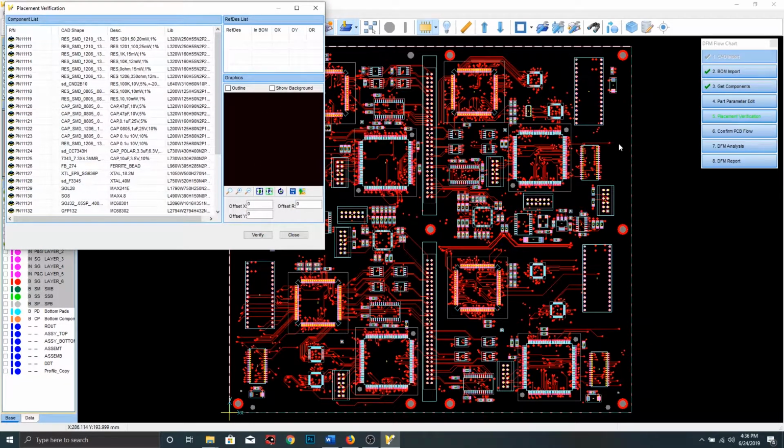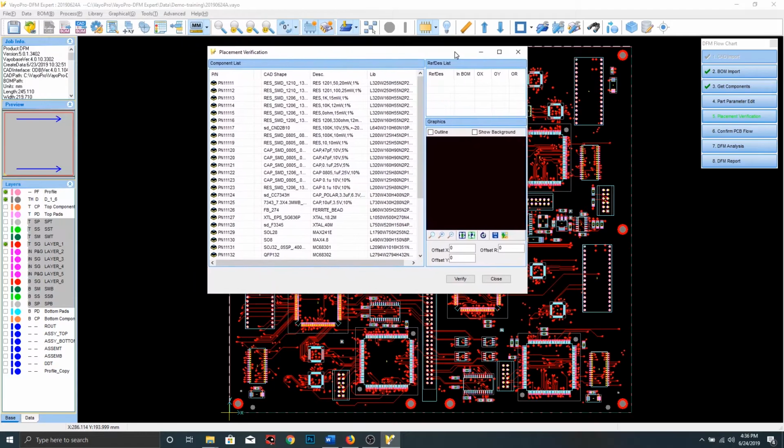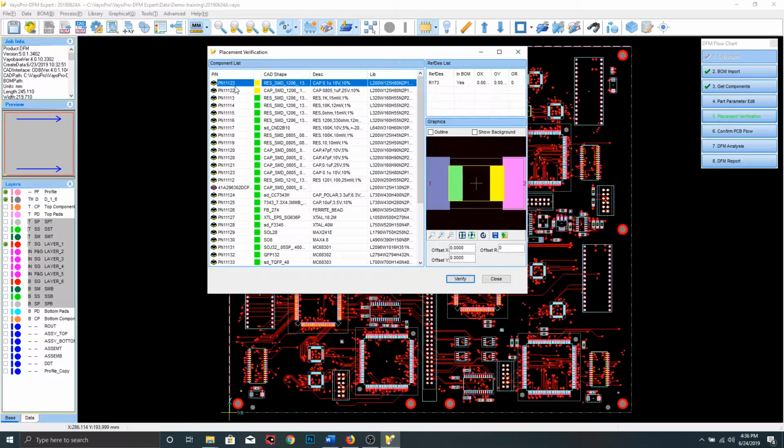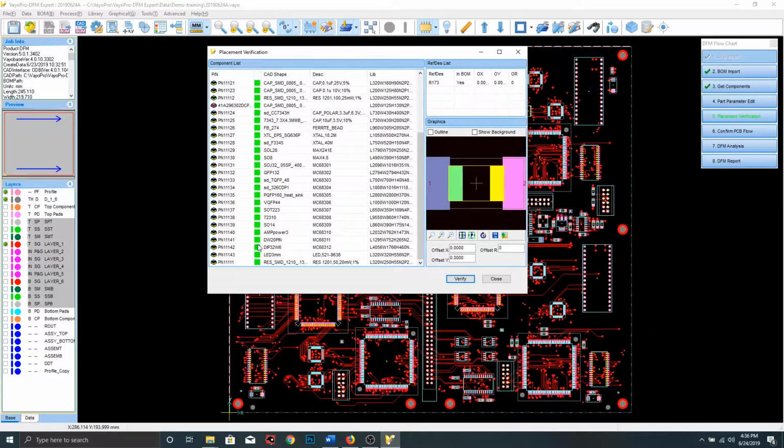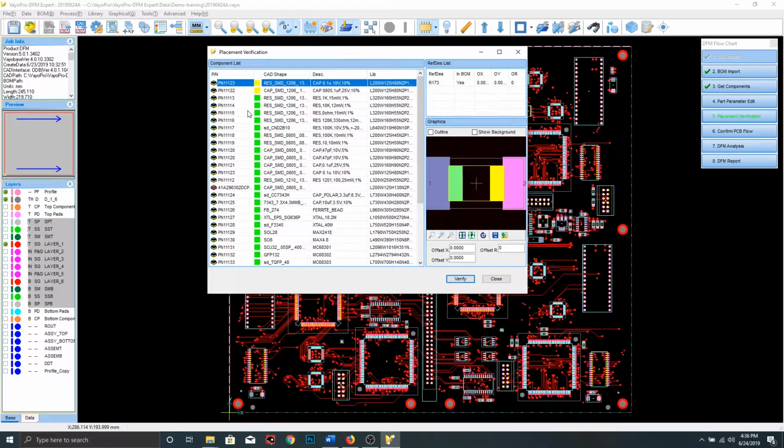In this step, we shall perform the virtual assembly and make sure each component is assembled with correct rotation and position. In just one click, DFM Expert will automatically correct the part's mount, rotation, and position. Here, DFM Expert also captures 2 obvious package mismatch problems. Let's save them to the final report. Using this function, we can find out major assembly mismatches and meet prototyping DFM DFA analysis needs.